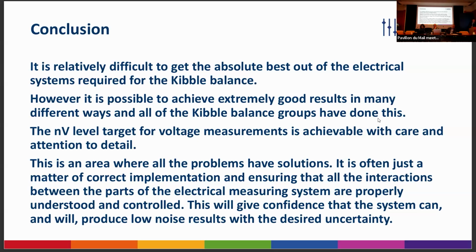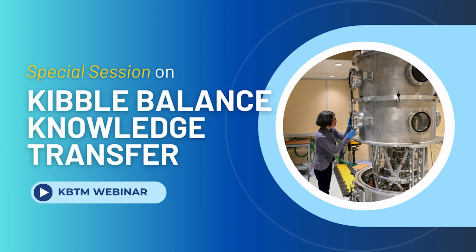So you know really what's generating a voltage, and where any interfering currents can come from, because it is better to have everything isolated properly so you don't get problems with ground loops and other things like that. There shouldn't be any ground loops. And if you get to that state, you can be confident that the whole system is working properly and will produce low noise, accurate results.